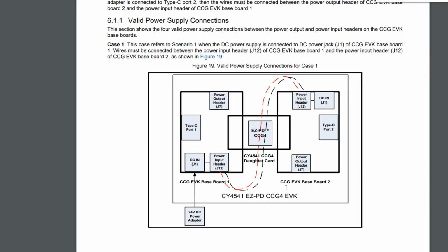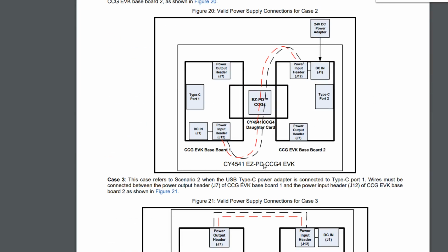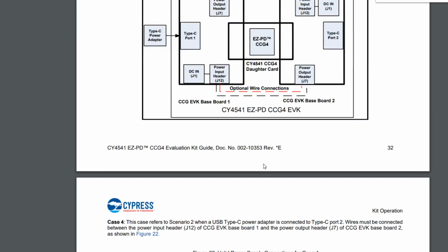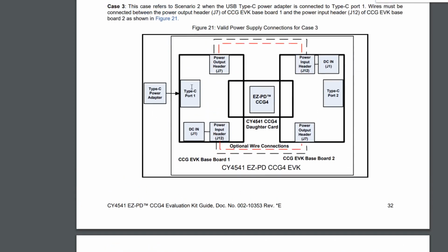Power output. And if we go down, we look at the USB-C case, where this requests either 5 to 20 volts, 15 to 20 volts. It has to request a high voltage, 15 to 20 volts. Now the 15 to 20 volts appears here, the same that appears here. Now at the output header there won't be anything, absolutely nothing.